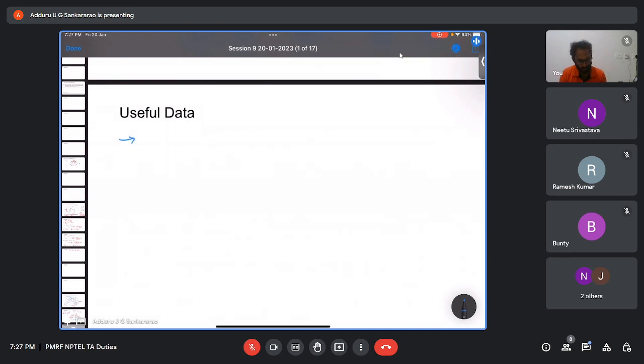Now at t equal to 0 plus, or you can say at t equal to 0, at the time of switching action, the capacitor acts as short circuit and the inductor acts as open circuit. At steady state, the inductor acts as short circuit and the capacitor acts as open circuit. At switching time, that is different.